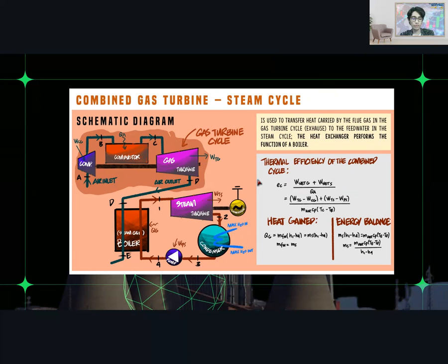The combined cycle power plant is the assembled heat engines that work in tandem for the same source of heat, converting into mechanical energy. On land, when used to make electricity, the most common type is called combined cycle gas turbine or CCGT plant. The same principle is also used for marine propulsion, where it is called a combined gas and steam or COGAS plant. Combining 2 or more thermodynamic cycles improves overall efficiency, which reduces fuel cost.